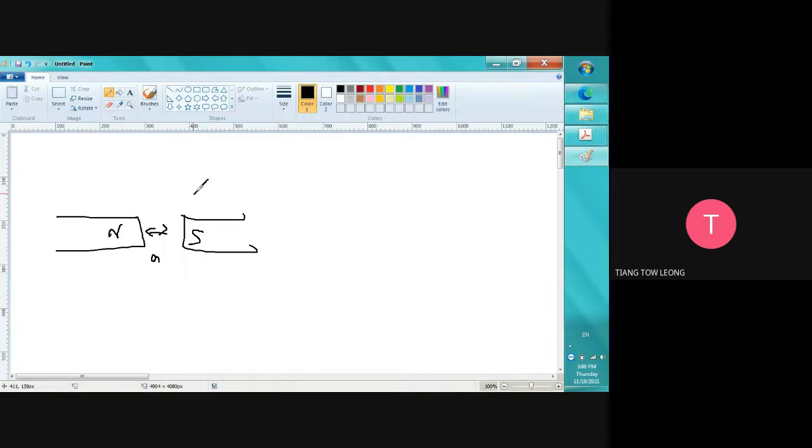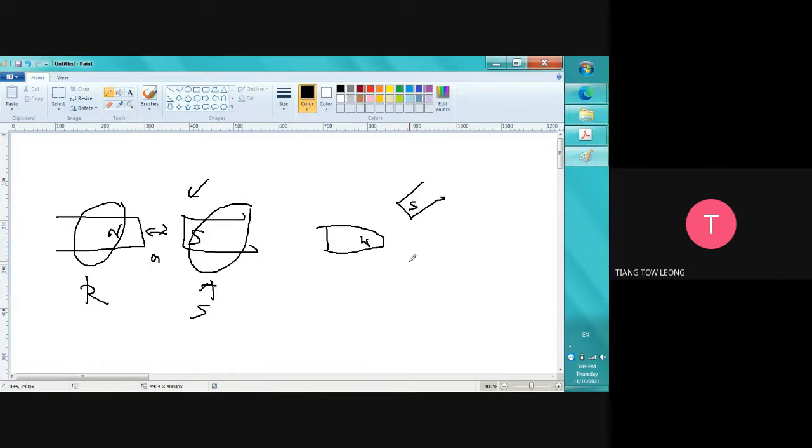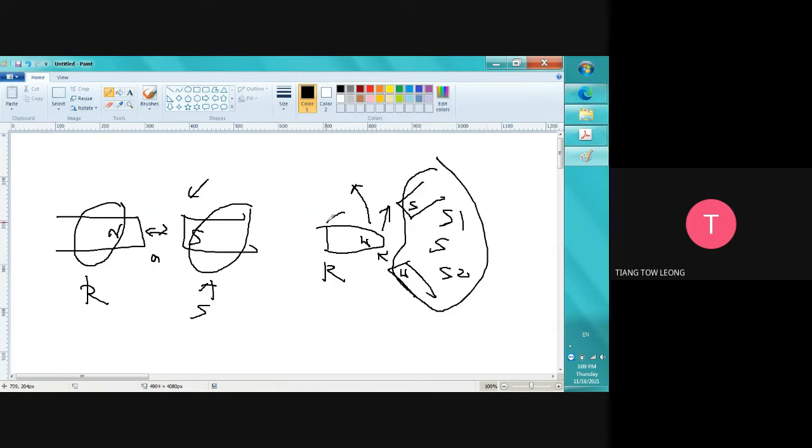So we need to have two fields. One we call the excitation field. One is from the stator field. One is static, one is rotating. So sometimes we might put it like this. This is north, and then south is here, and then we put a north for the stator. Let's say this is stator 1, stator 2, so that one is attracted to there, one is pushed to there. So it will rotate in this direction. Now this is the rotor, this is the stator. Okay. Next.